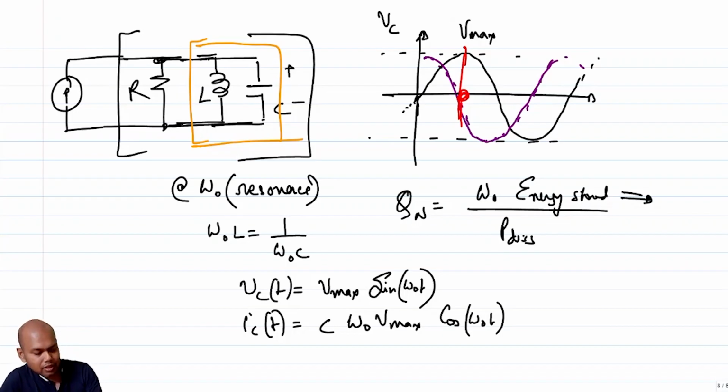It is the current in the inductor and the current in the capacitor being exchanged, right? So if I check the total energy in the tank at any point of time, I take half CV squared for the capacitor voltage and half Li squared for the inductor current, and add them up.